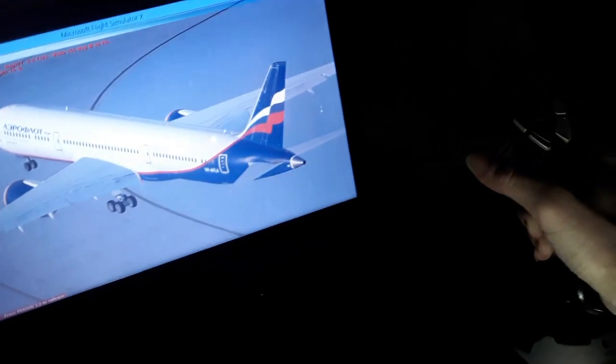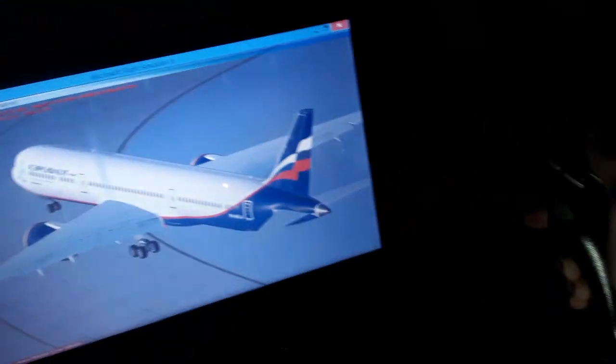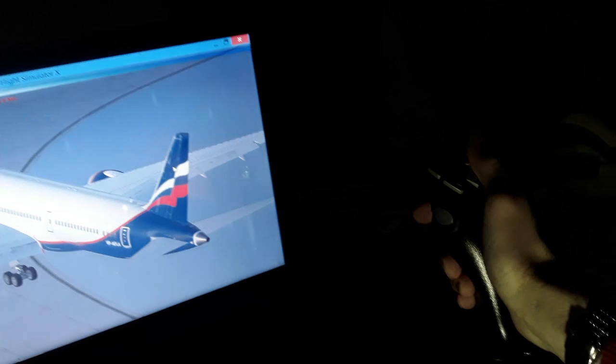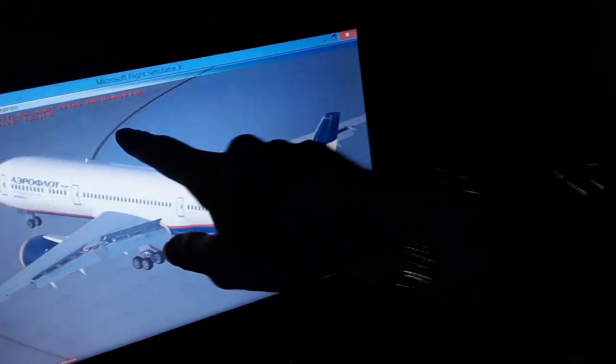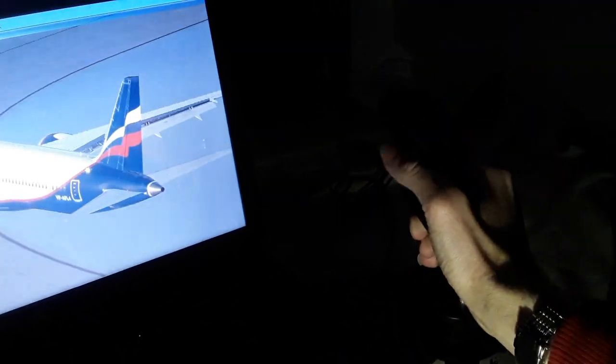So these are all the flight controls you need to know for flying the aircraft. You can see the tail movement over here. Also we have the nose wheel steering on the ground, which also affects the yawing axis. That's why it's controlled by the rudder pedals and the tiller on the ground. I'll talk to you later about how we control the rudder and the nose wheel steering together.